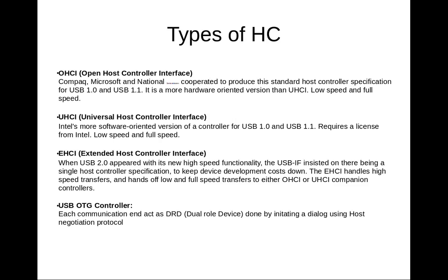And EHCI came when the new generation of USB came into the picture with high speed functionality, which was lacking in OHCI and UHCI, and it was implemented by USB-IF. Basically this was a new thing for USB 2.0, and to have backward compatibility, it has companion host controllers like OHCI and UHCI connected to it.